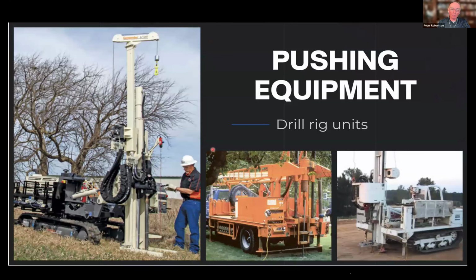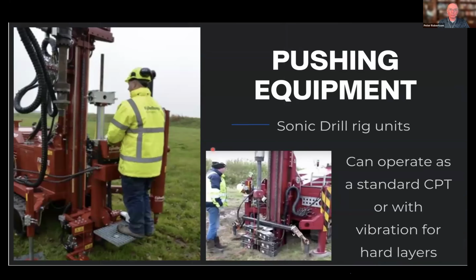But there's also where you can take an existing drill rig and modify it to push CPT. So these are examples here. And then in recent years, sonic drilling is becoming very popular. So one of the companies in the Netherlands that makes sonic drilling realized that it would be nice to add CPT to a sonic drill. And so they built a little hydraulic ram set that would fit in the chucks of the sonic rig. And you could do a static CPT to whatever depth you're able to push in.